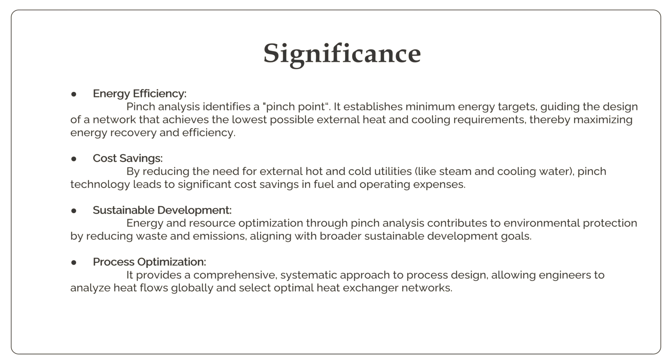The significance of pinch is that it identifies the pinch point, which establishes the minimum energy target for maximum energy recovery, and it also reduces the cost by reducing the external utility. We can save the cost. It also achieves sustainable development.